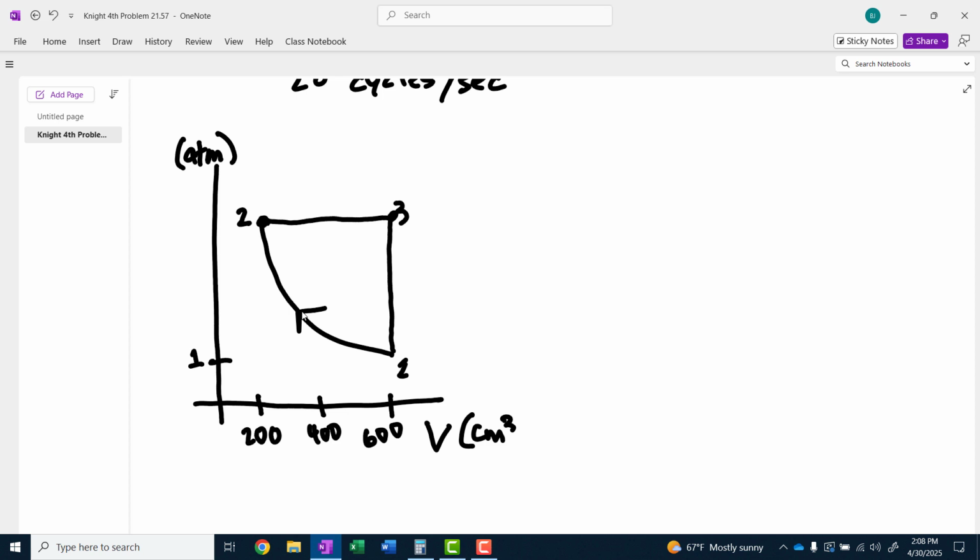In general, as you squeeze a gas, wouldn't it tend to heat up? And yet, in this case, we're doing an isothermal process. So the only way for the gas to stay at the same temperature while you compress it is for heat to flow out. So I'm going to draw a red arrow indicating that the Q for this process is a negative number. Heat is flowing out in order to maintain a constant temperature.